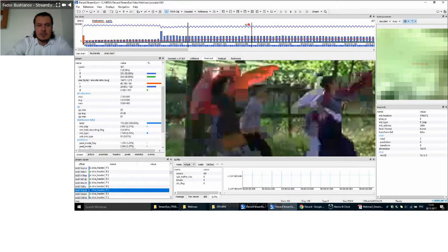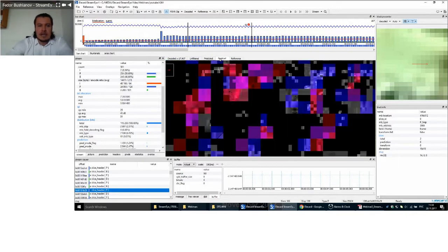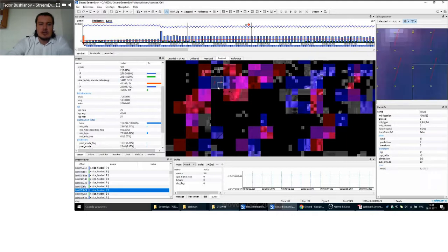Again, this is the decoding stage where we reconstructed all the macroblocks on the current picture using prediction information from the previous frames, but didn't yet add the difference information between the current frame and the reference frame. That information is called residual.